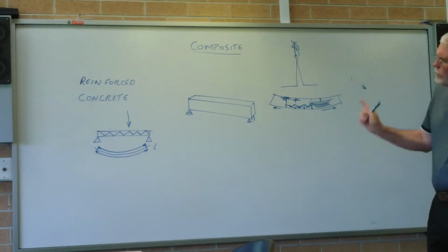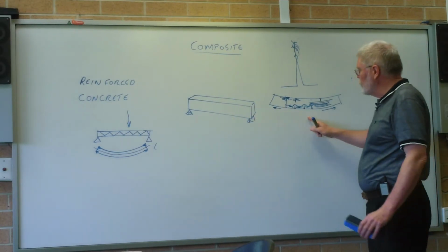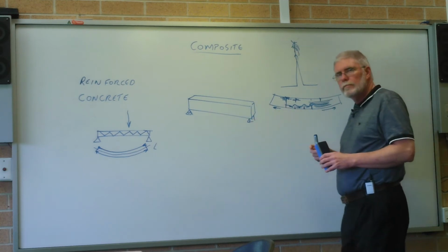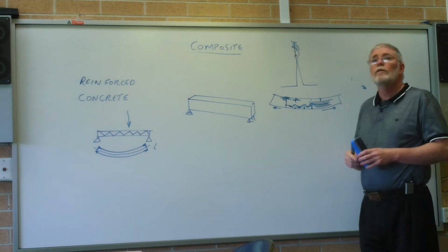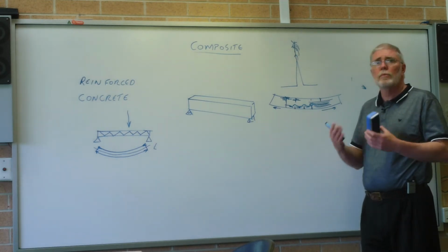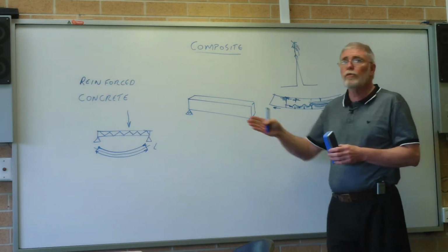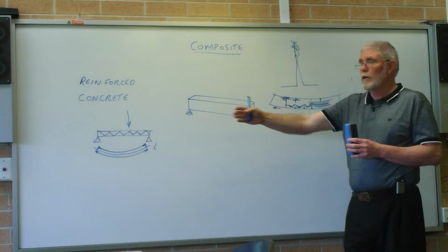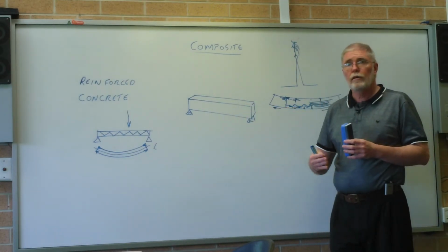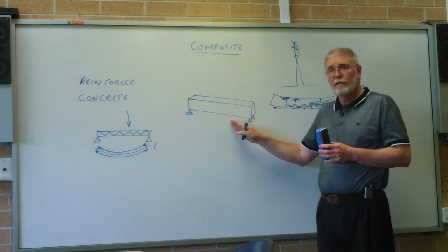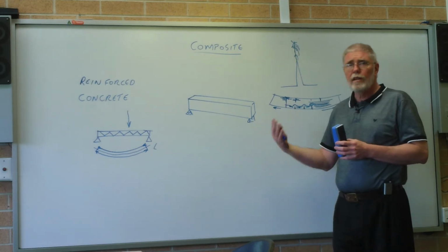So, that limits how we can use our concrete beam. The further you go, the longer the beam, the more pronounced the curve, the bigger the arc, the more open the cracks, the more likely it is to fail. So now we're back to timber was a problem because it was limited in length because trees aren't too tall. Now we find ourselves limited in how far we can go with concrete. Because if we go too far, and concrete is heavy.